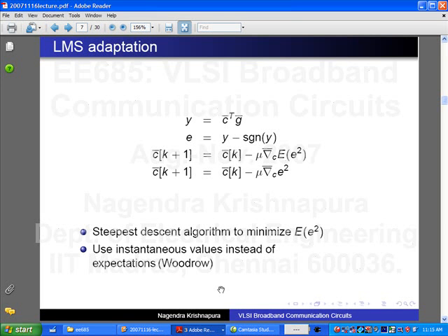It turns out you can make an adaptive zero forcing equalizer also, but from the point of view of equalization, the LMS equalization is better. The filter minimizes the mean square energy of the intersymbol interfering elements. That is better than zero forcing, and for adaptation it also turns out to be easy. So essentially you use what is known as the steepest descent algorithm.